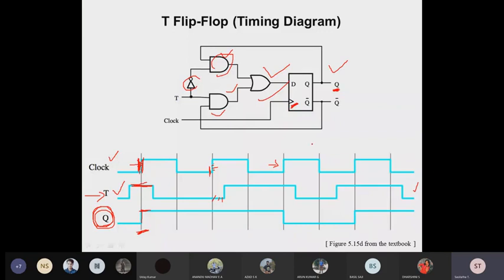So that will result in the delay, and you might have received some previous pulse information. Then finally, again, you have received some positive edge trigger, and you could sense the information as positive, but it's not the reflection of this exact T input value. This is nothing but the reflection of this respective T input value. Since there exists some propagation delay, this will get reflected at this location.